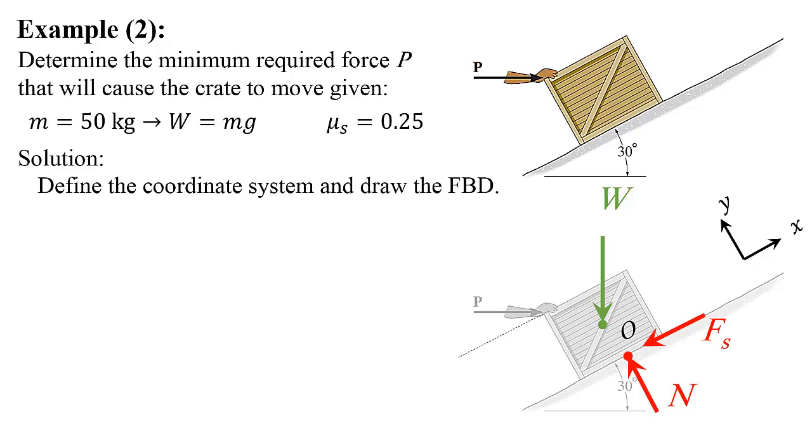Any other force that's not along the coordinate system I chose, I have to resolve into components that go along the x and y directions I'm defining here. So W is always pointing downwards, and now I have to resolve W into two components as shown, and of course P has to be resolved into two components as shown on the figure.